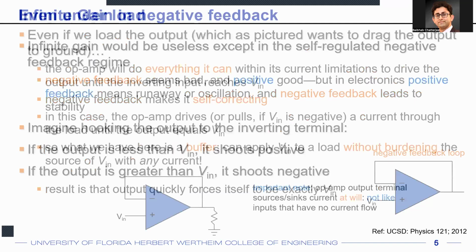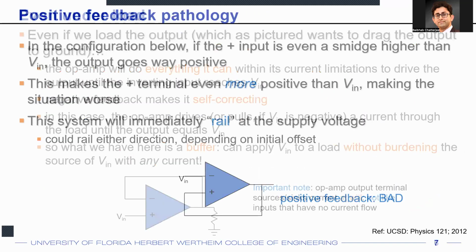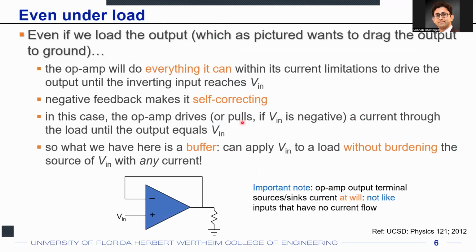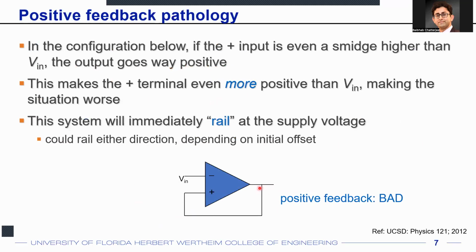Okay. Now, you can have positive feedback or negative feedback, as we had discussed earlier. Negative feedback means you'll take the output, feed it back at the negative terminal of the input. That's what it will essentially boil down to. For positive feedback, you'll take the output, feed it back at the positive terminal of the op-amp. And we're saying that positive feedback is bad. That is bad in terms of amplification, because eventually with positive feedback, you might run into oscillations, which you may not want for an amplifier.